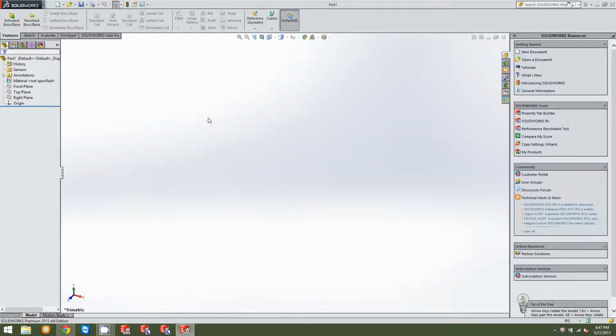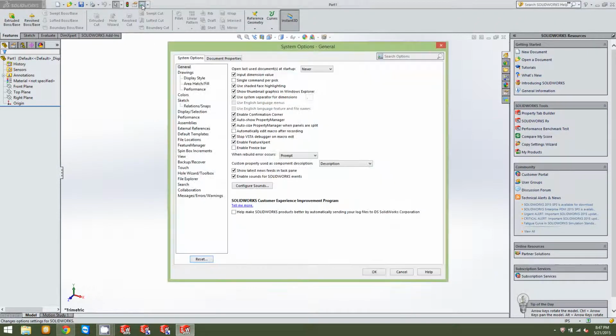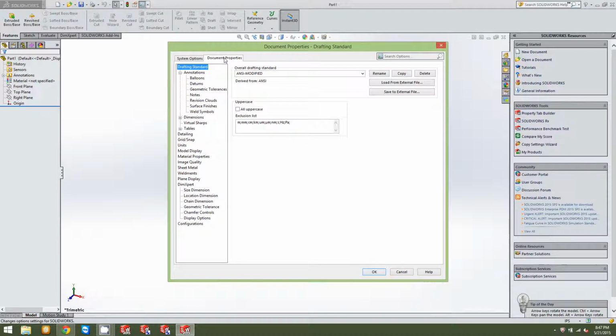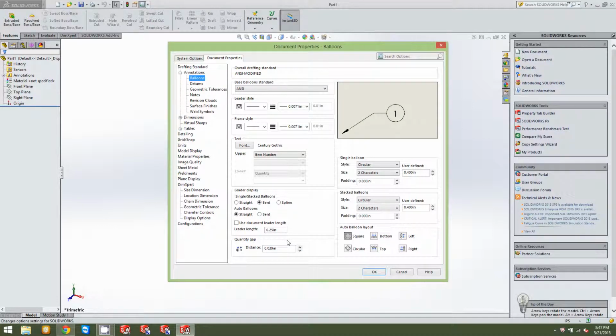Oh, that's a critical mistake. This is something you'll probably do over and over again, just out of habit. What happened there is I hit enter after I punched in the size, so it closed out my window. When you punch it in, don't hit enter, just click out of it in a different area. Come back over here, 0.125, click out of that. Now it's shortened up that landing on the bent leader, and I'd say that's about what I'm going to go with on that one.